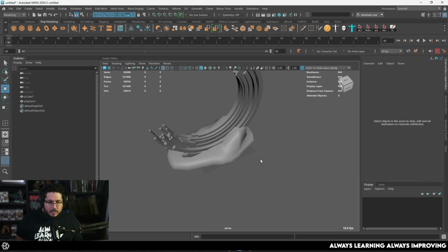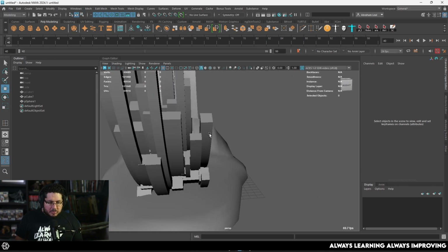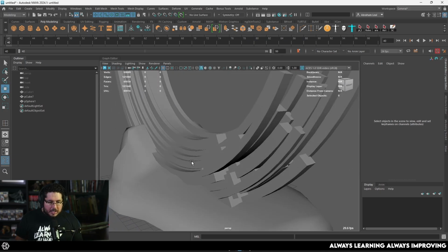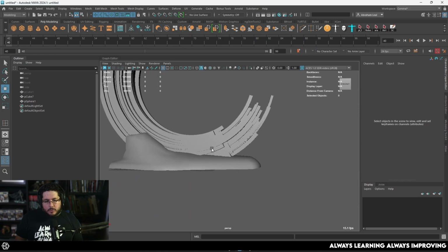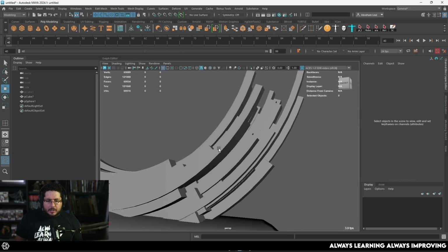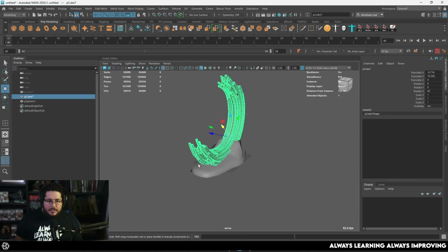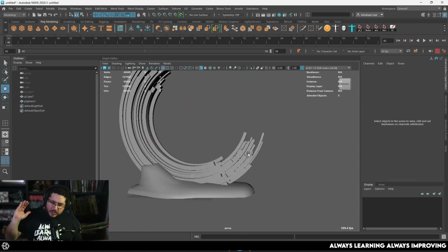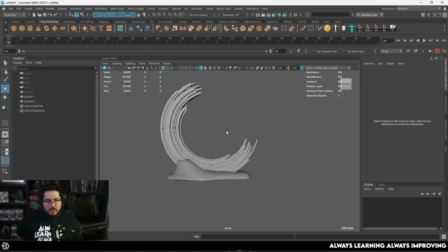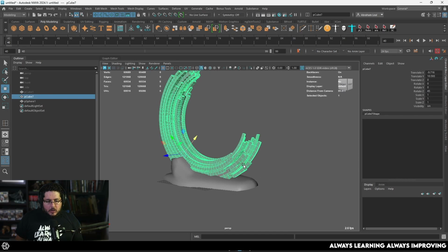I really like this one. It's looking quite nice. And again, from experience, I know that all of this is going to print just fine. Barely any support. Why? Because the way 3D printers work, at least resin 3D printers, is as long as a curvature follows the same path of the element, you're going to get a nice result. And in this case, that's what's happening here. So unless we have very crazy overhangs, which we don't in this particular element right here, you're not going to have to do that.